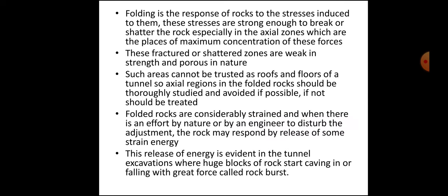Such areas cannot be trusted as roofs and floors of a tunnel, so axial regions in the folded rocks will be thoroughly studied and avoided if possible. If not, they should be treated.